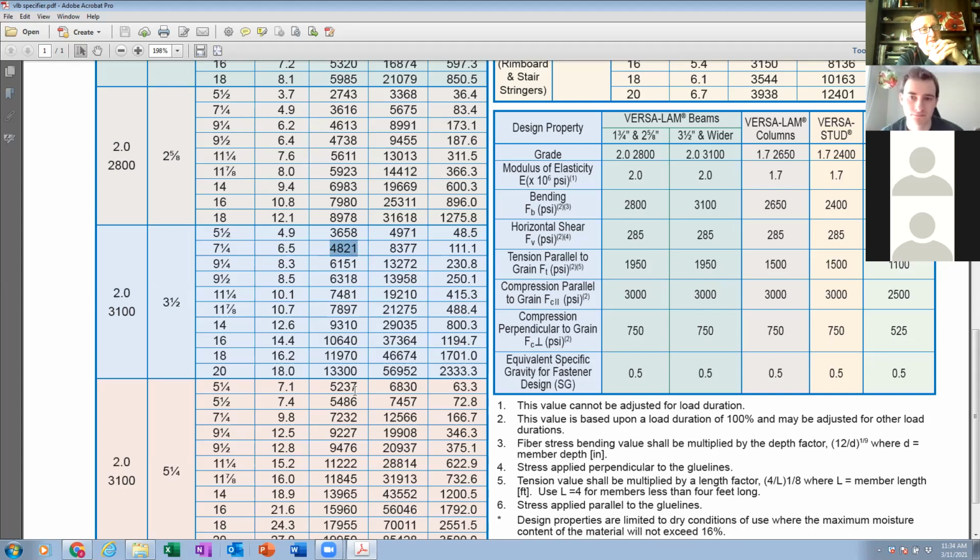This is your job as an engineer. You've got to look at that load, and I showed you how those distributed loads actually get applied based on the weight of floors and the projects we did. I showed you where those come from. You've got to be the one that chooses the beam. And so shear is one of the components you've got to figure out. It's the internal structure of the beam. Is the beam strong enough to resist the fact that it wants to slide past?